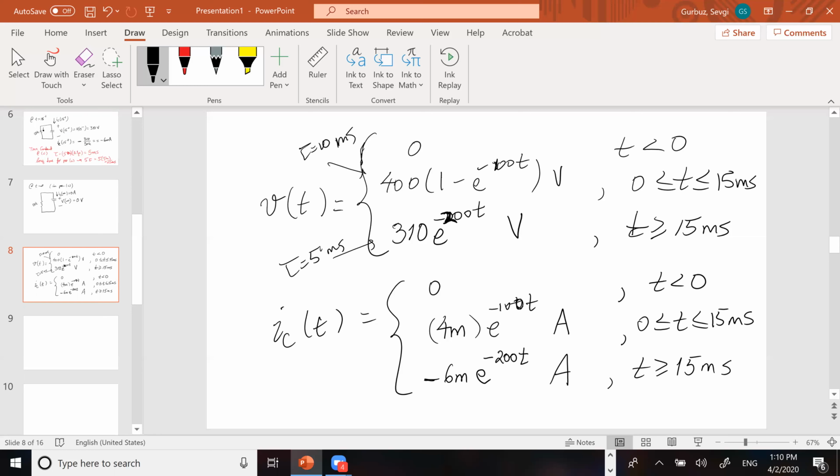Okay, so you can see that there's a number of important considerations. The main 3 things that you need to calculate over every interval are the initial value, the final value, and the time constant. You write the equations as though there were no switchings and it just stayed in that position forever. But in the cases where you do have a switch which interrupts it, notice how that is taken into account by these updated initial conditions when we're starting the second interval.